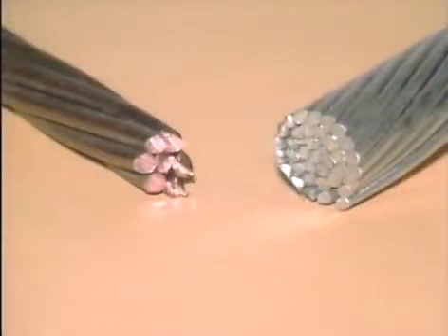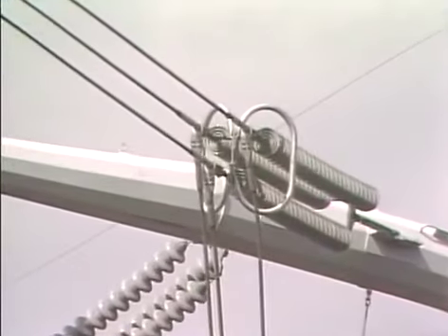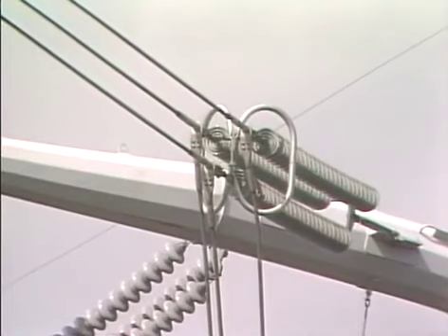And you should always be sure to handle conductors with care. Avoid nicking, bending, and dragging conductors to help reduce corona effects. You should also be sure to install and replace devices such as corona rings and spacers in accordance with your company's specifications. By doing these things, you can help keep power loss to a minimum in your systems and ensure transmission lines that operate as close to design specifications as possible.